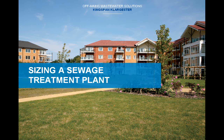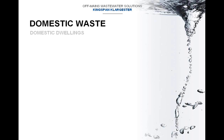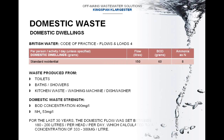Sizing a sewage treatment. Sewage is split into 2 parts, domestic waste and commercial waste. Dealing with domestic waste first, this is basically the flow as you would have in a normal household. The flows range from 150 litres per person per day, using an organic load of 60 grams of BOD and an ammonia load of 8 grams. Waste produced from toilets, baths, showers and kitchen waste, washing machines and dishwashers.